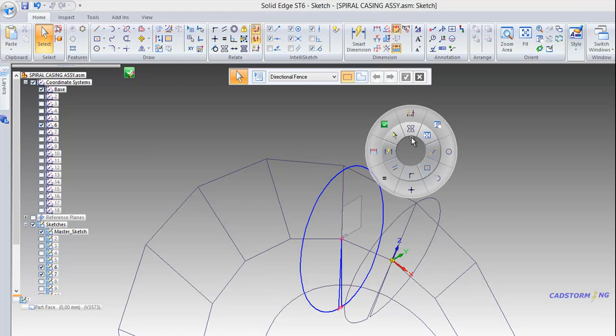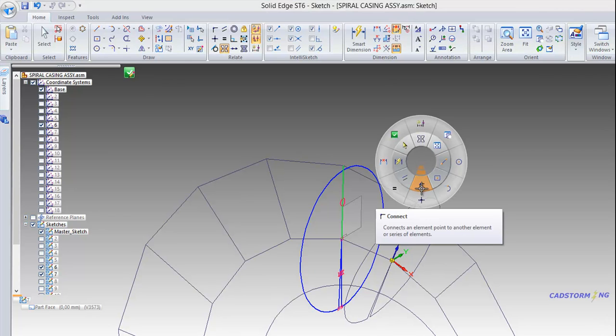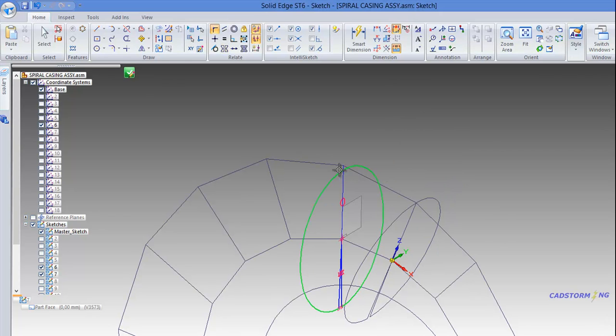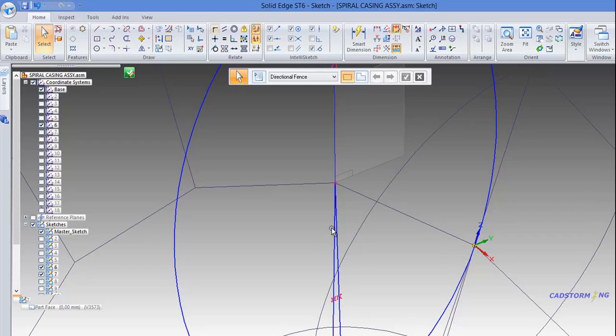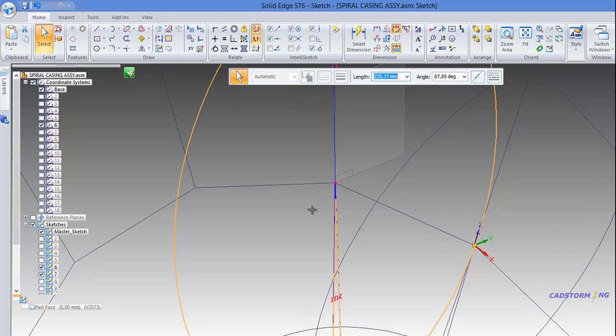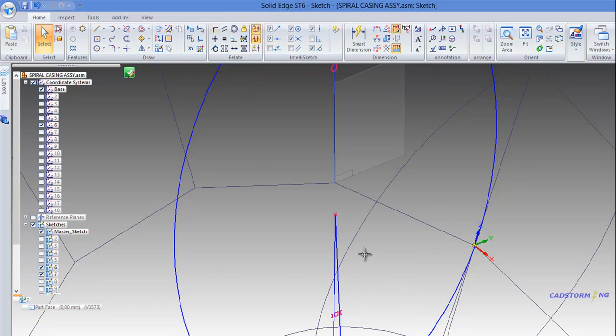So symmetric, just activate the radial menu and select the axis, the first element, second element, and then connect, look for the middle, connect it there, and maybe I should start with the relationship assistant, but for now I could just move this one and use the connect again.